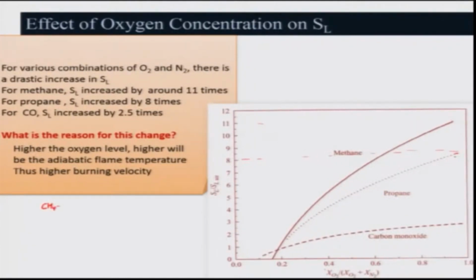This is CH4 air, the adiabatic temperature in Kelvin will be 2210, whereas if I use pure oxygen instead of air, then I will get 3030 Kelvin.